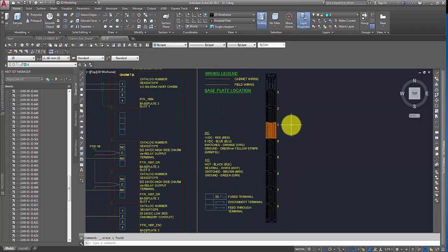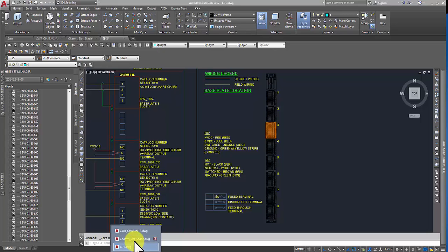In this case, what we've got is a DeltaV project using the CHARMs electronic marshalling. So we can see the rack elements here. We know that an individual rack for CHARMs can only have 8 modules. And so what we're doing now, when we're putting together the loop drawings, is shading one particular element. So let's jump and have a look at the templates.